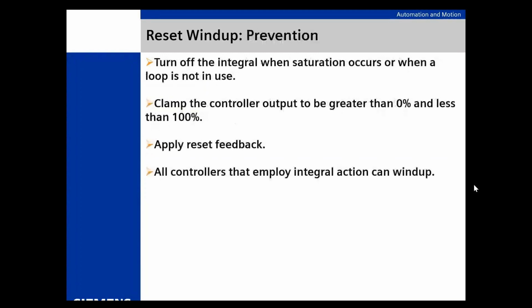All right, there's wind up prevention right here. We're kind of past time. I'm going to have to speed this up a little bit. Turn off the integral when saturation occurs, when a loop is not in use. That's an excellent thing to do.